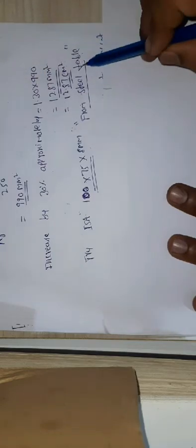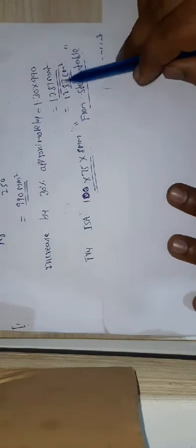After calculating the gross area required, we need to increase it by approximately 30%. Increasing it by 30% means whatever area I get should be multiplied by 1.3. So in this case I got 1287 millimeter squares. If you convert it into centimeters, it will be 12.87 centimeter squares. Now you need to select the angle section by using the steel table, for the required area.